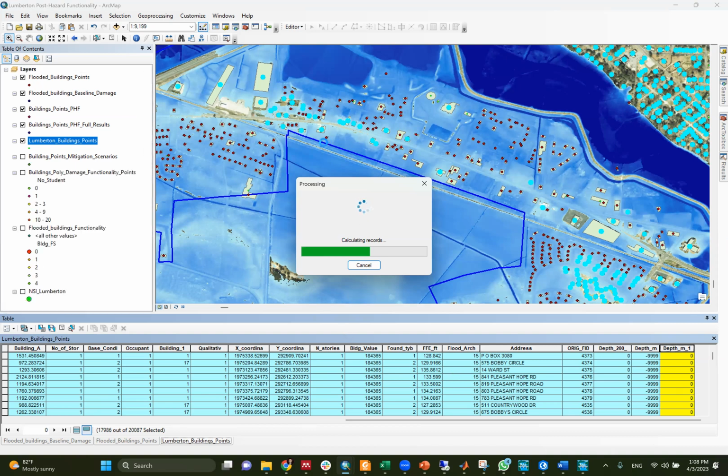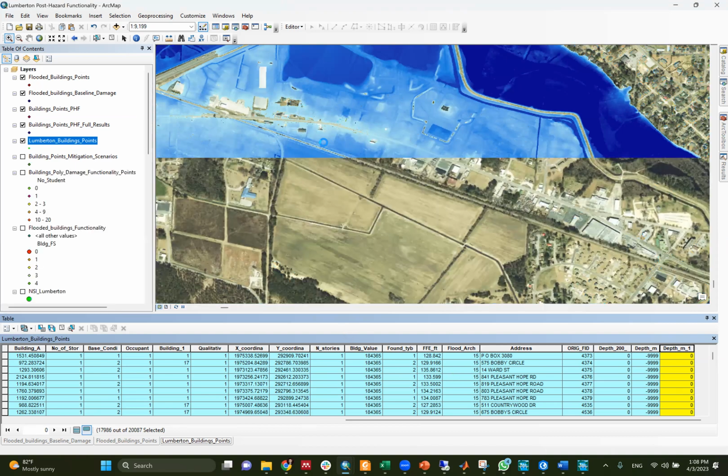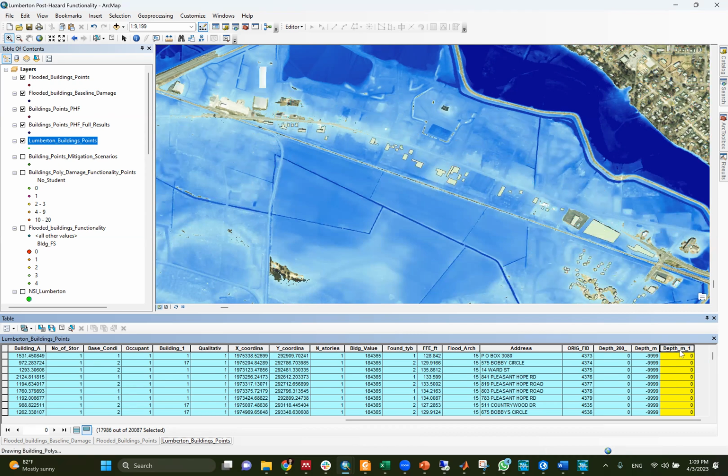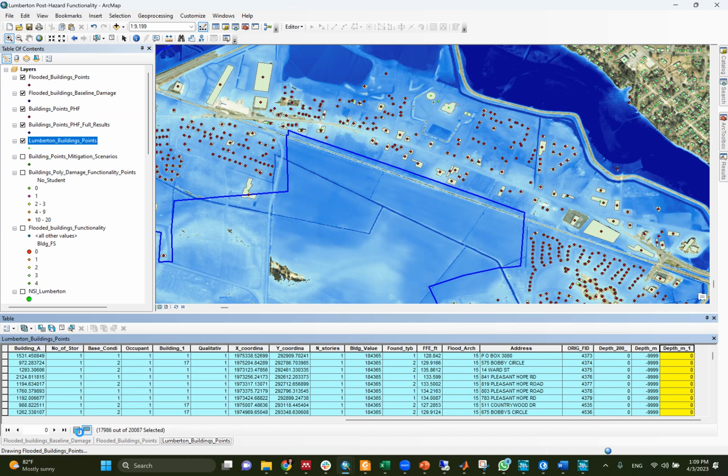Same thing like wind: if you have a wind speed hazard map, you overlay it with the buildings and extract the whole thing. Okay, so right now I made these 0. Why did I change them to 0? Because if you run your MATLAB code over the 20,000 buildings, it can run because it has flood depths of 0, and 0 is embedded in the fragility.